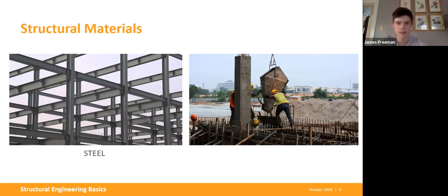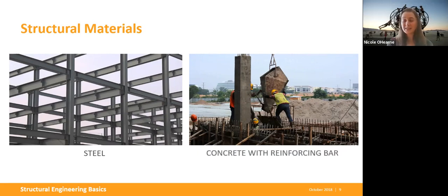Yeah, it's rebar, exactly. So rebar is made out of steel and it usually has these grooves on it so that when you pour the concrete into the form, you get a bond between the steel and the concrete. And the form is usually the wood casing that they pour the concrete into.